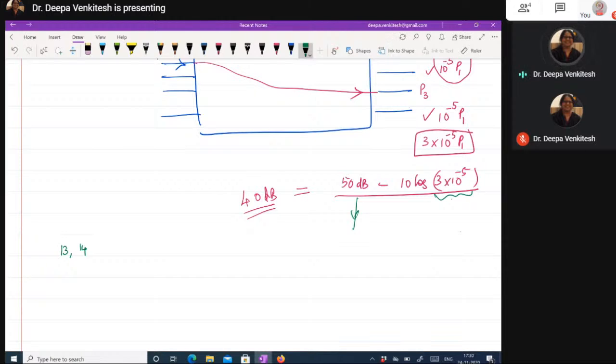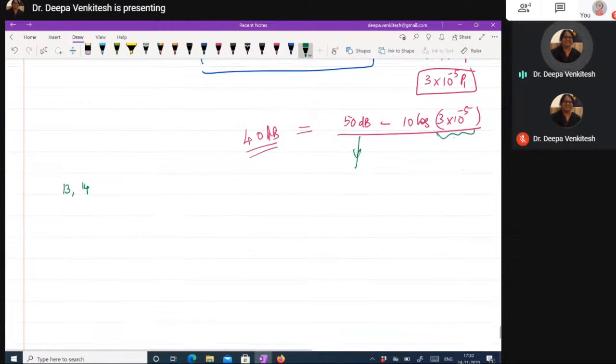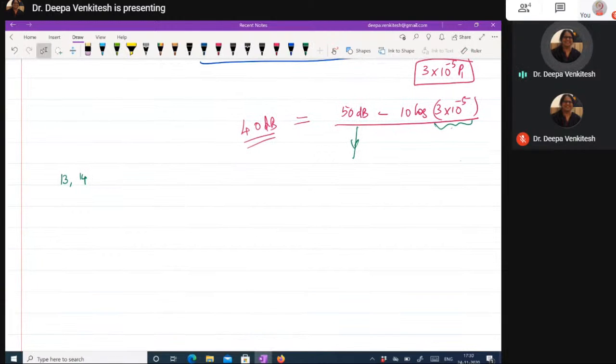There's no figure, sorry. A 2x2 biconical tapered coupler has a 40-60 split ratio. So you have a coupler with 0.4 P1 and 0.6 P1 appearing here.